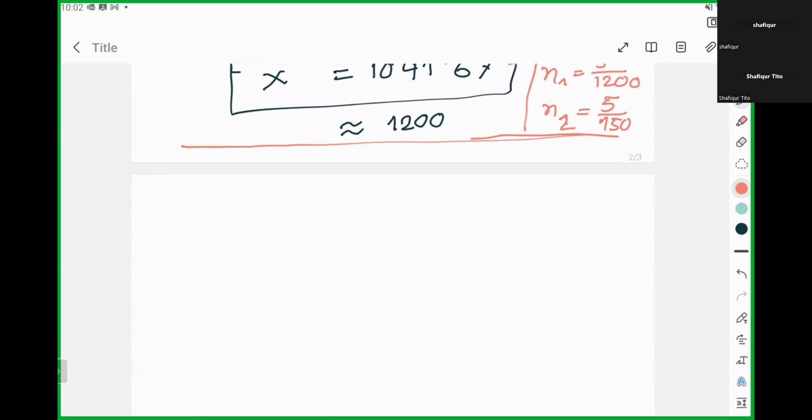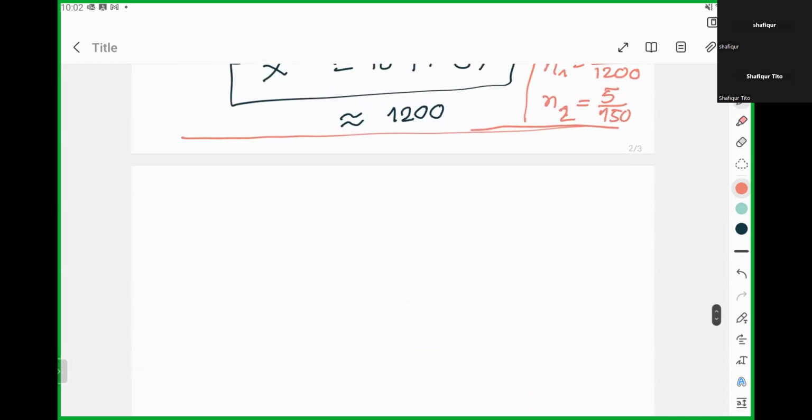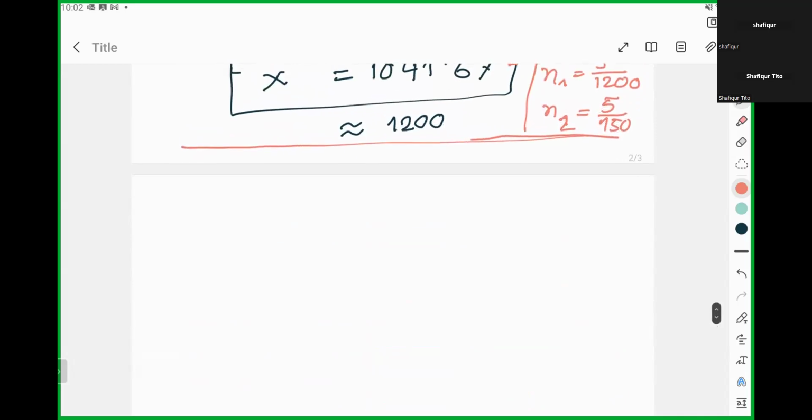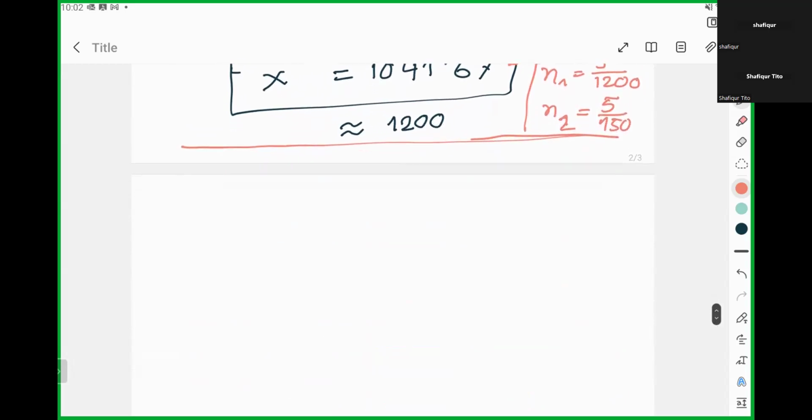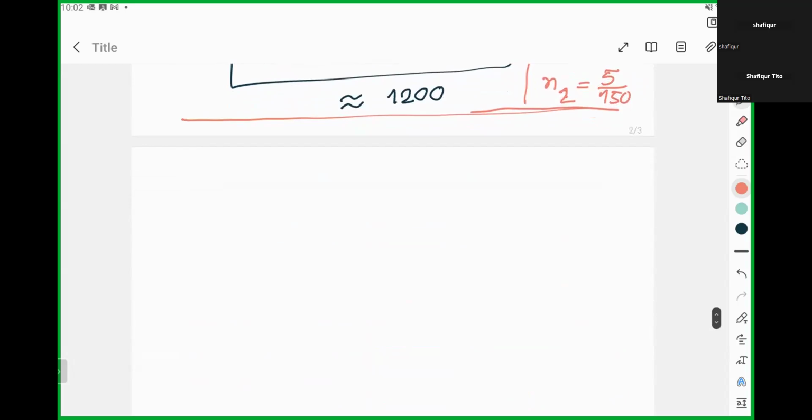And we need to find out what would be the slope of the characteristic curve, so that this mismatch can be nullified. In order to do that, I need to first find out what is the actual current in phase due to this turn ratio. So 5 divided by 1200 times 502.044 ampere would be the current for this new turn ratio, and that will be equal to 2.